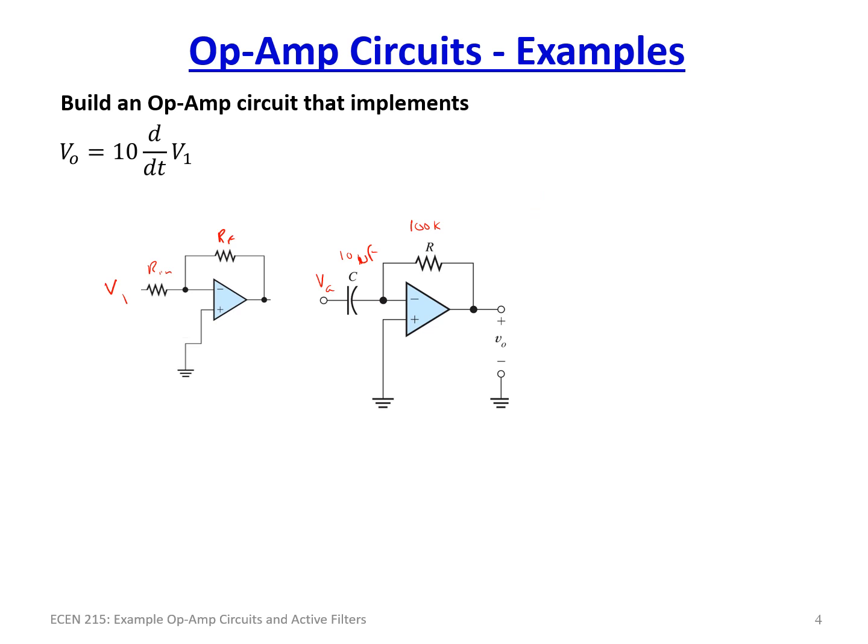Okay, so now what about this? Well, correspondingly, we need this output in the end to be 10, so we're going to want RF to be equal to 10 kiloohms. And therefore this needs to be 1K, leading to a gain of minus 10K over 1K here times V1, and of course this is connected to here.